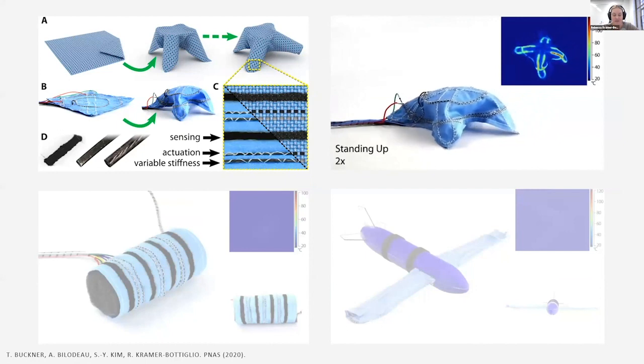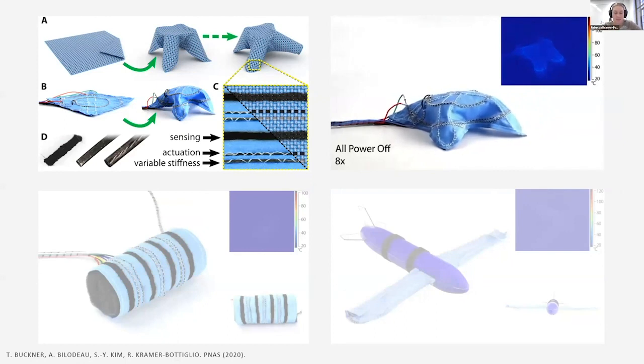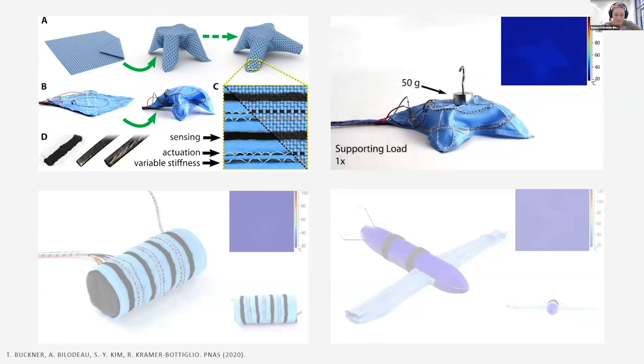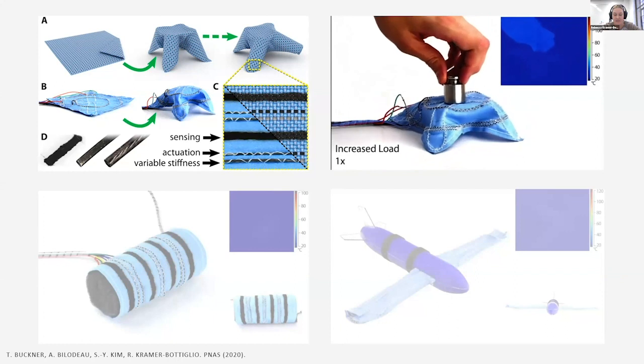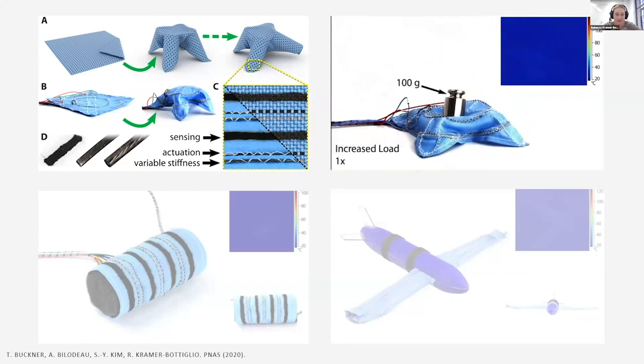First, we demonstrate a shape-changing robotic fabric. The initial form is flat, and upon activation, the fabric softens and its variable stiffness frame lifts up to a table-like platform. The new shape becomes rigid and load-bearing, as demonstrated by weights being placed on the surface. And the shape is then returned to its initial flat configuration using an antagonistic ribbon actuator.